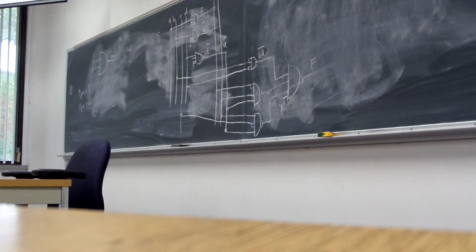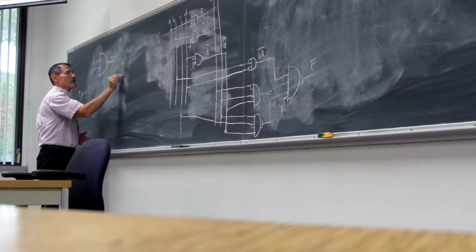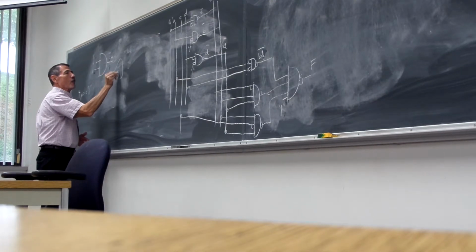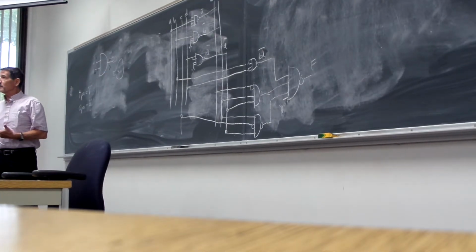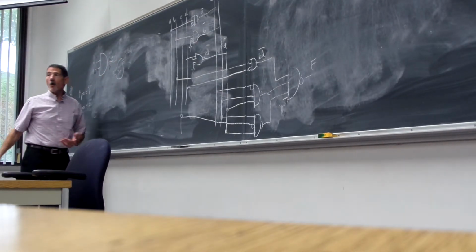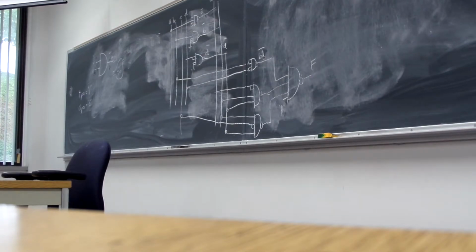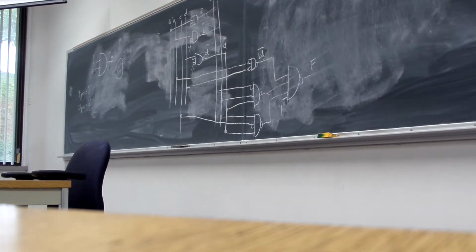For example, my balloon, I'm going to puff up my balloon here, and so it's going to blow up to 4 psi, right? And I want to maintain that, yes? But my stupid balloon has got a hole in it. It's got a pinhole in it. Therefore, what has to happen if I'm still going to maintain that 4 psi? Constant flow. You got to keep putting more air in.